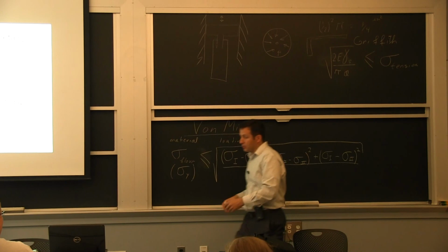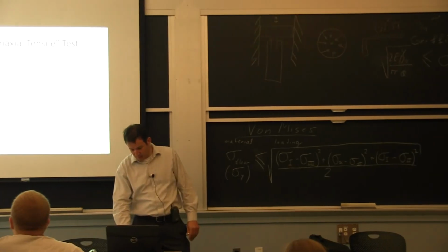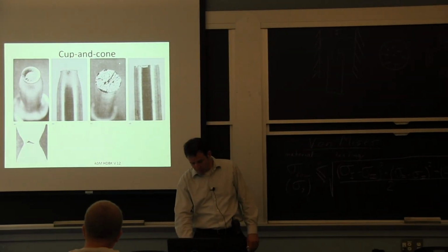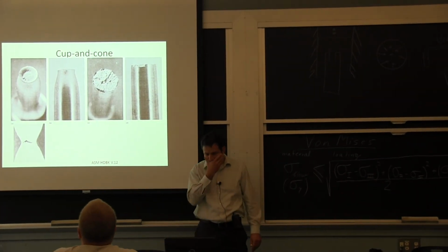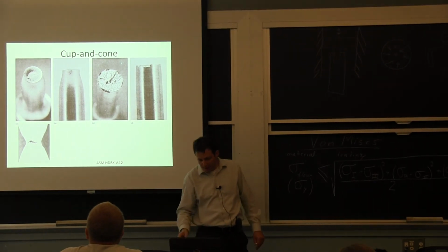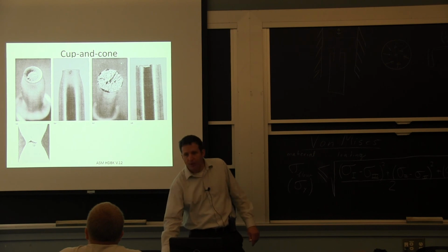that we can talk about the most is the difference between a tensile specimen and when you do these impact tests. So the tensile specimen, we talked about quite a bit. You form this cone and cup structure. And this was something that some of you were a little surprised about, the cracking starting in the middle.